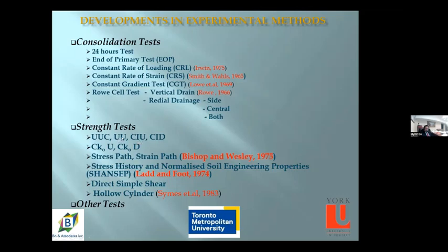However, in situ soils are not unconsolidated. They are consolidated under at least the overburden pressure, and some of them are even over-consolidated due to past history. That's why geotechnical engineers developed the isotropically consolidated undrained test.